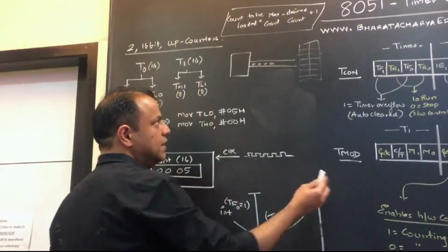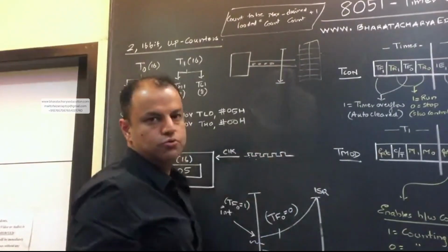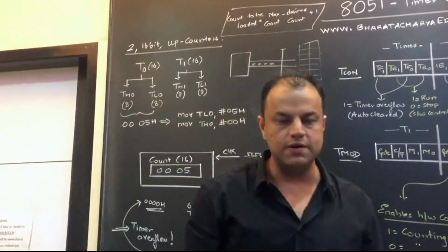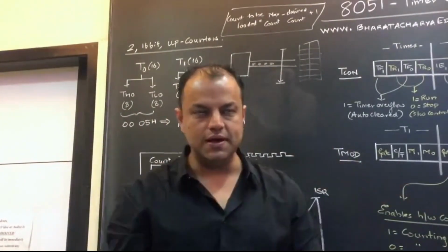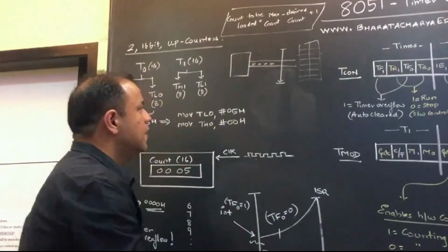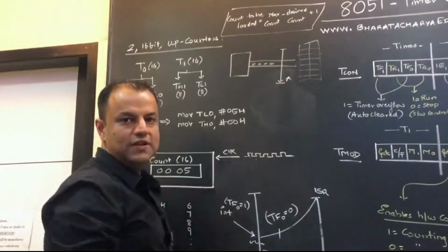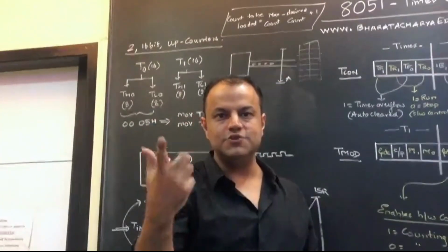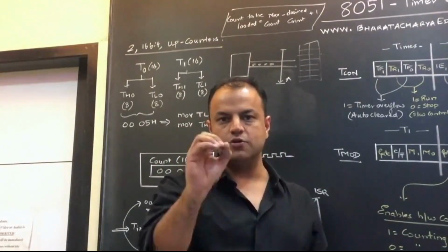So in the modern era today, this is done by a laser light. It can be UV, it can be IR, whichever one you want. Mostly it's IR, but it can be any of the two. You know, pure is what we see, the others we can't. So infrared light. So this is a transmitter, this is a receiver. The receiver is a photocell. A photocell means the moment you throw light on it, it gets charged. So let's say it becomes logic 1. When light is not falling, it is discharged, logic 0.